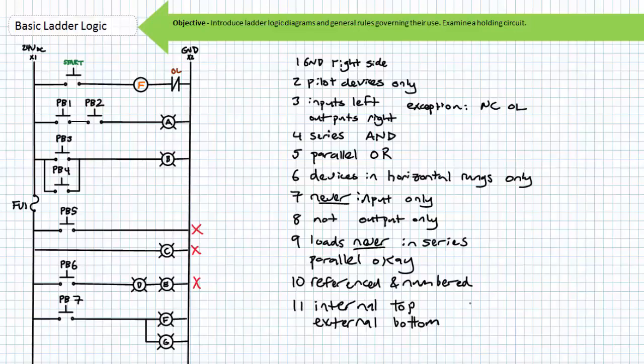An example might be an electrically controlled system using a control relay, a timer, a counter, a solenoid, and a pilot lamp. The control relay, counter, and timer, since they perform internal logic functions, would be in the top half of the ladder logic diagram, and the solenoid and pilot lamp, since they are observable external outputs, would appear in the bottom half. Again, this will make more sense as we extend our analysis into increasingly complicated electrically controlled systems.